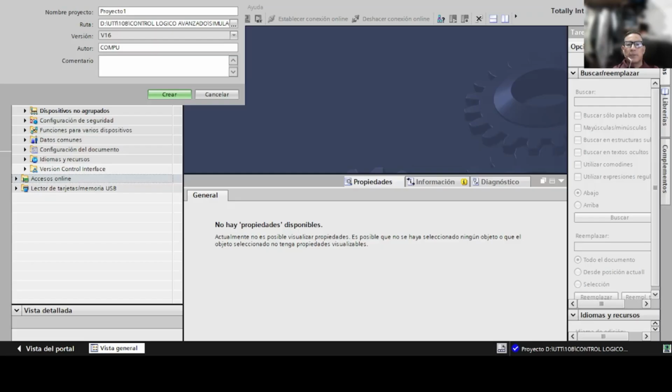Today we are going to build a complete industrial automation project titled Tank Level Control with Siemens S7-1200 and LabVIEW. We will program the automatic filling and emptying of a tank from scratch, establishing a minimum and maximum level. And we will control it all using a custom SCADA interface.